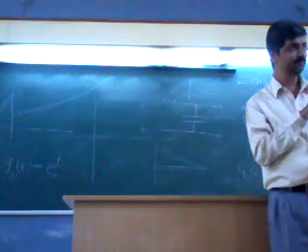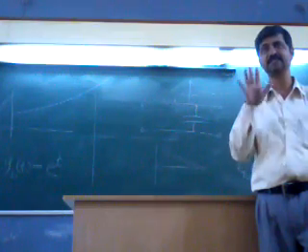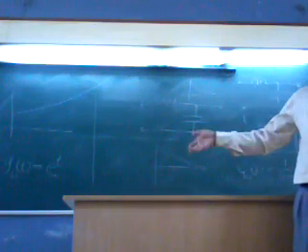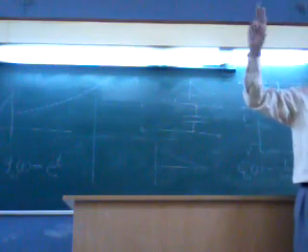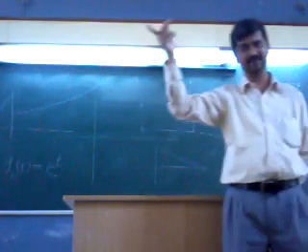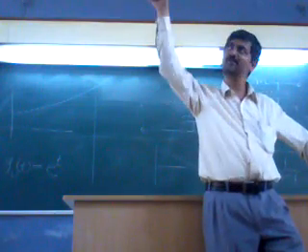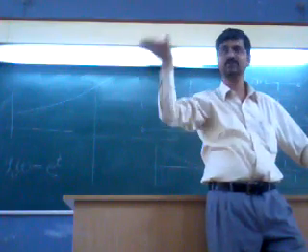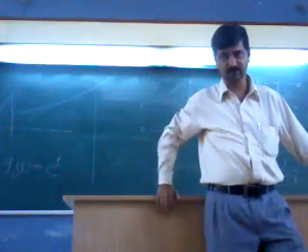Are you getting me? Finding out the roots of a polynomial is a tedious task. So without going for that direct finding, the Routh criterion provides us, just by looking at the coefficients, some kind of number jugglery by a fixed standard method of writing down the coefficients in a given order, and there is a simple method to be followed that will tell you whether the system is stable or unstable. That I am leaving up to you. Right?